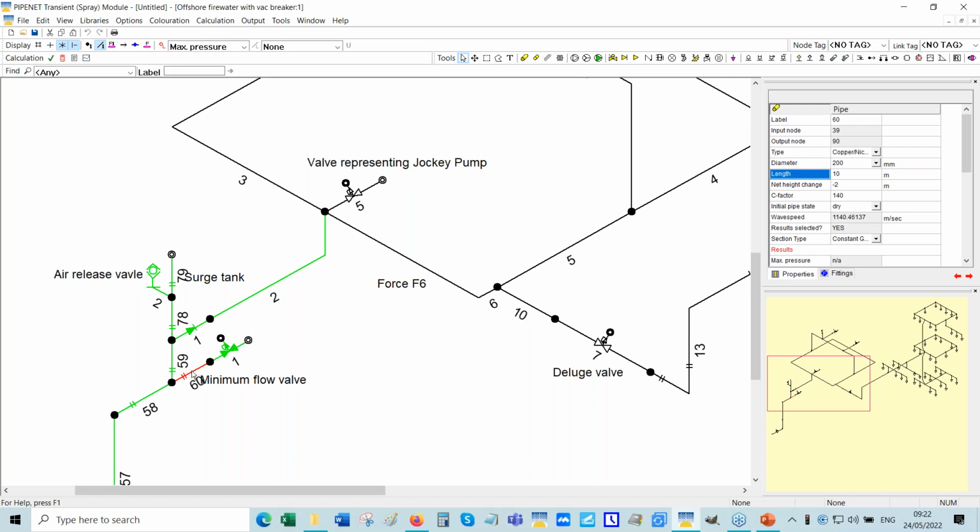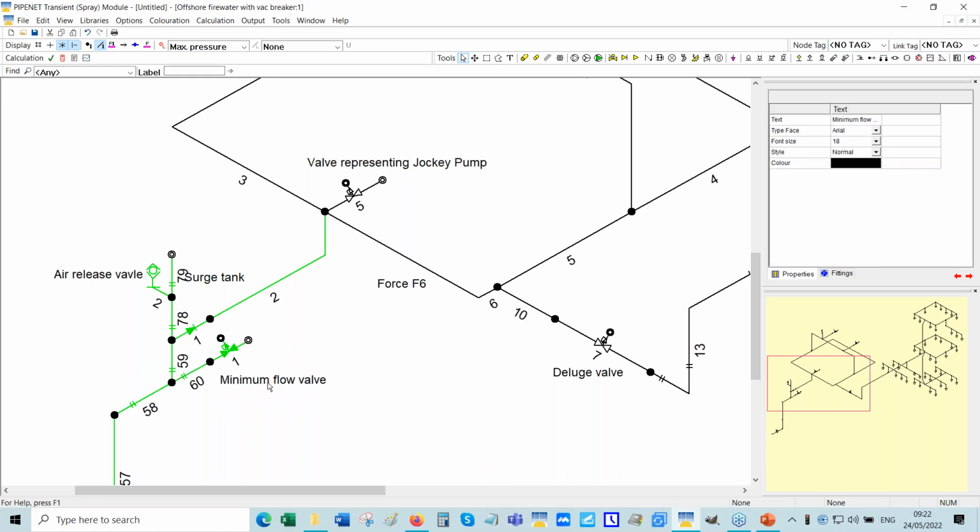Maybe you should use a shorter pipe here, because what happens is water actually hammers into this dead end. There's an air column here that's highly compressed, and then it stops oscillating, and hence this is a source of pressure surge. It was quite an unexpected discovery for me. So anyway, that is how you model the Frank Mohn pump, or the company is now called Framo, I believe, not Frank Mohn anymore. And this is how you model that pump.